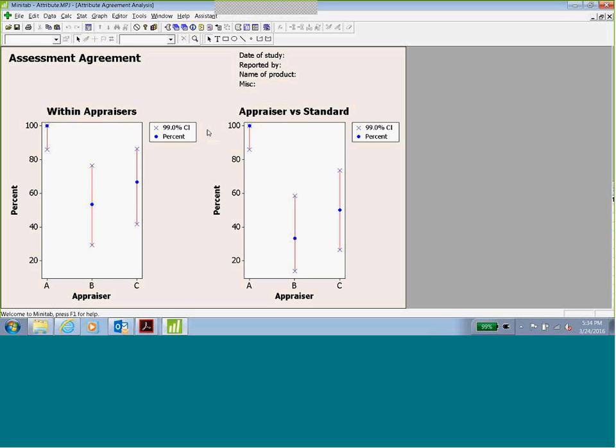So it's minimum 90 or 95%. The acceptance criteria is going to differ for different studies, but usually it should not be less than 90%. This itself you can clearly identify if the results passed or not. So in this case, I would say my gauge failed because on average, only operator A has passed. His results were good, whereas B and C did not. So failed the study here.